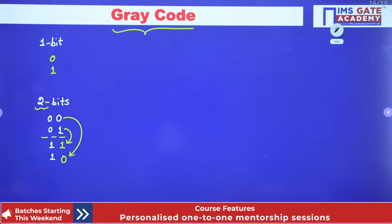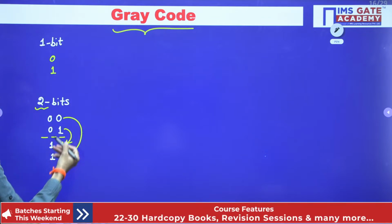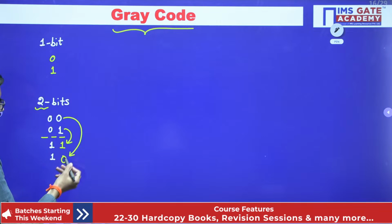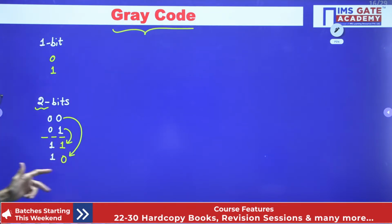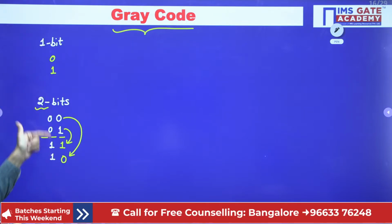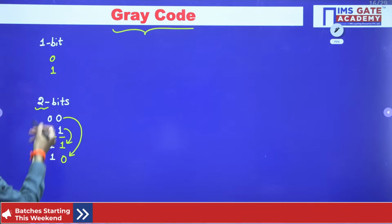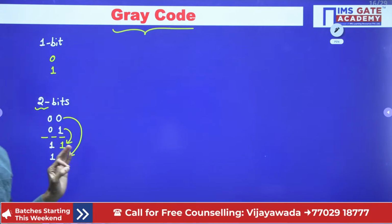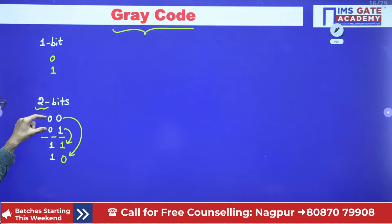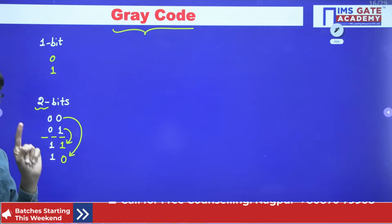Now you can observe here, 0 0 to 0 1, only 1 bit is changing. 0 1 to 1 1, only 1 bit is changing. 1 1 to 1 0, only this bit is changing. And even the last code and the first code differ in only 1 bit. So whatever code we arrange here, if you consider any two successive codes, only 1 bit differs.